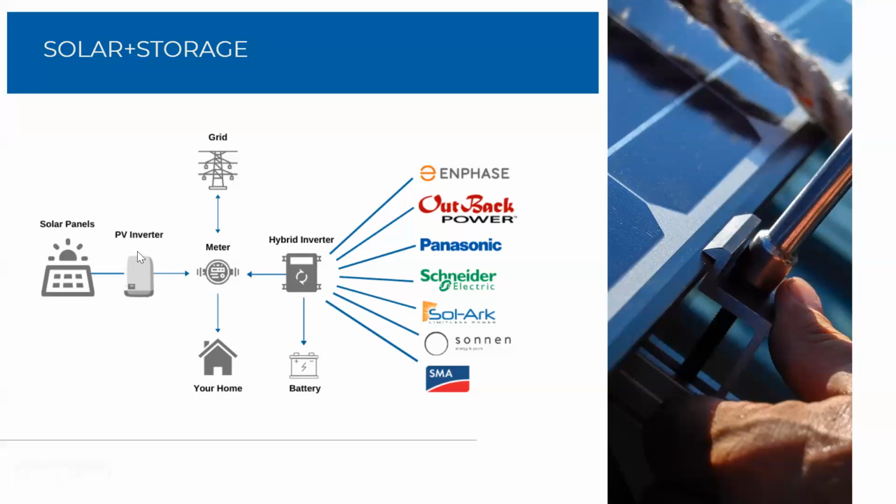When the PV inverter is on, typically you're feeding your main service panel. So 100% of the PV is feeding your house. In the event of an outage, if I only have a sub panel with a few select loads on my home, let's say fridge, lights, television, fans, Wi-Fi, those 5 loads will be physically moved to a sub panel, and then my PV will also be moved to that sub panel.